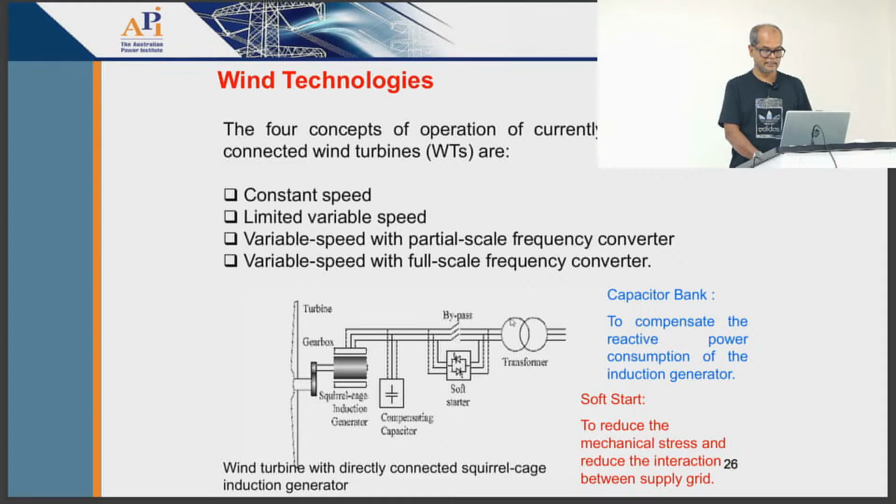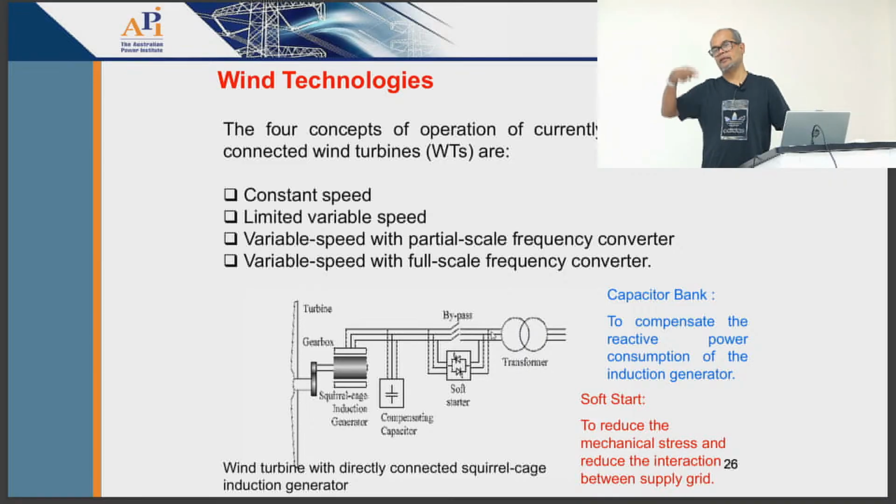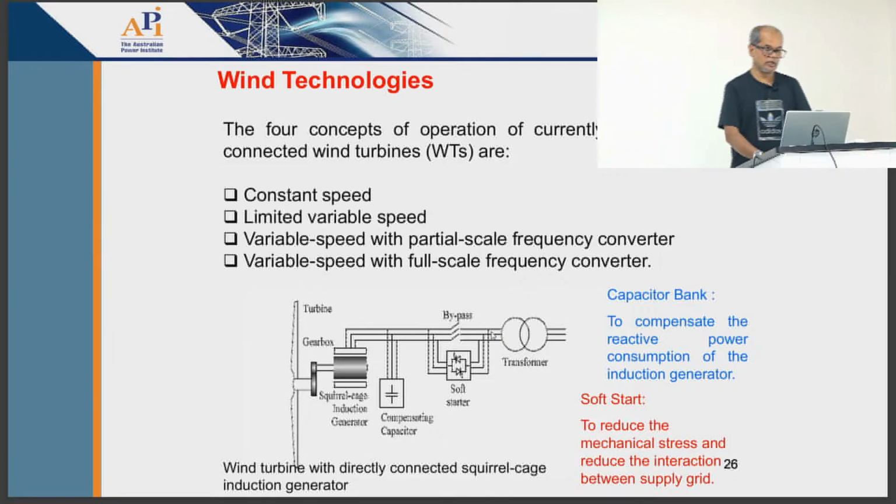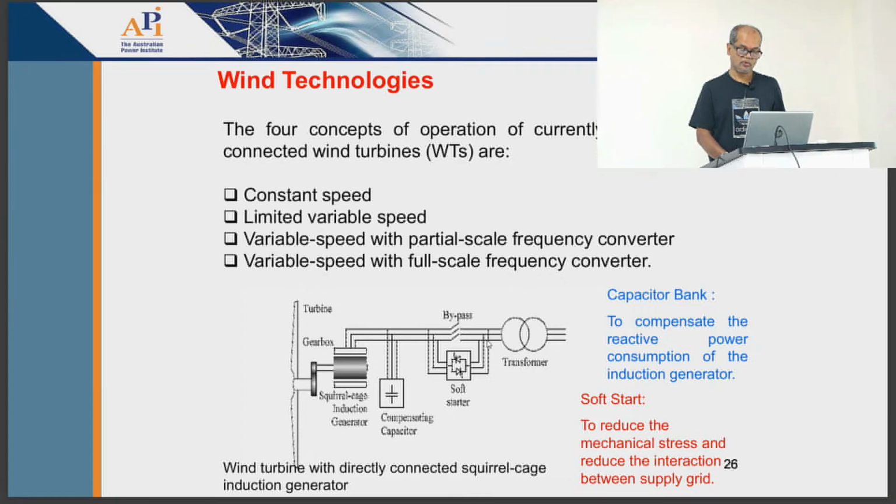That means this is limiting current coming from the grid. But once it spins and rotates close to the rated speed, it produces the back EMF. At that time current automatically reduces. So we don't need that additional resistance, because it's going to have some losses, because this is resistance. So at that time it is bypassed. So this is only used at the starting period, the beginning.